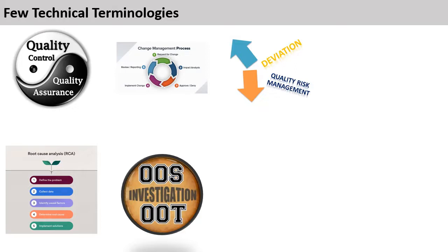Yes. CAPA means corrective action and preventive action. Corrective actions are the actions which are taken to eliminate the root cause of detected nonconformity to avoid recurrence of the same. Please note, it is for detected nonconformity and to avoid recurrence. Preventive actions are the actions taken to eliminate the root cause of potential failure to avoid occurrence, means first-time occurrence of the same. Now understand the difference. CA is for detected while PA is for potential nonconformity.